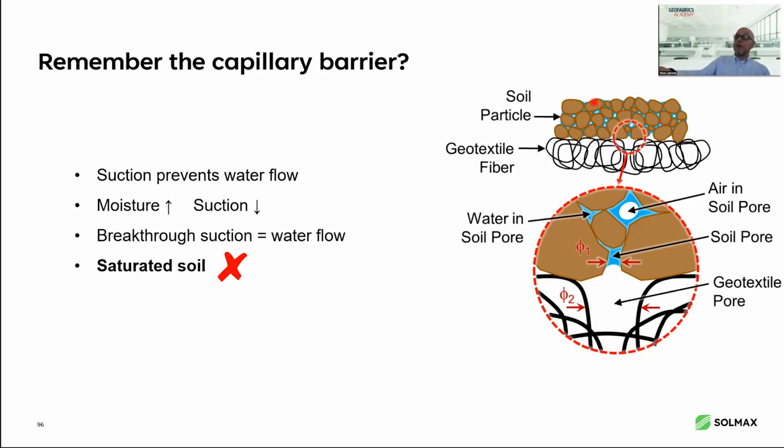And it became saturated because, if you remember those percentages, just before the water traveled through, the moisture content was 15%. Then as the water was traveling through, it was 30%. But the breakthrough moisture content here was 44%. And so that means now it's completely saturated.